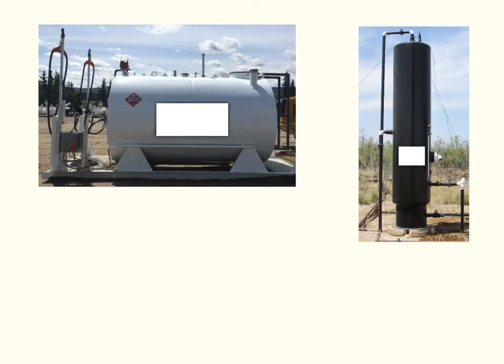Often when we're wiring above ground tanks, of course, we have to come up from underground in most cases. Now, it is important to realize that many of the liquids that we're transferring, like gasoline, have a high vapor content, and that vapor content actually has a tendency to be heavy and migrates below ground. And therefore, even though we might be ordinarily looking at, let's say this is a Zone 2 location, depending on how far we are out from the pumps, right below that is not a Zone 2 location where we come up with our conduits and our fittings.